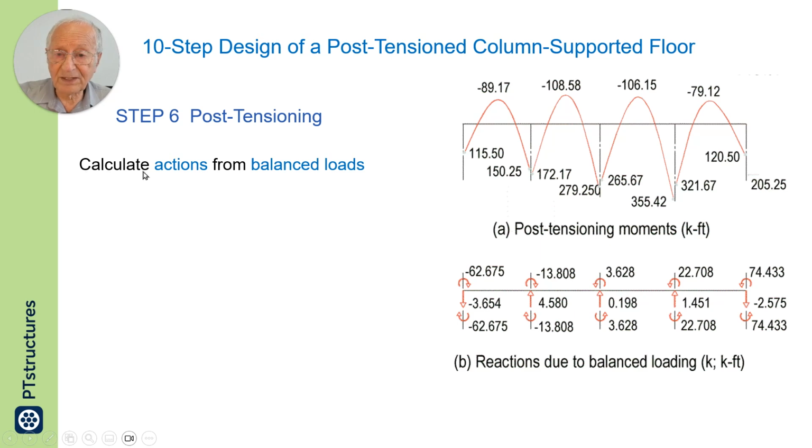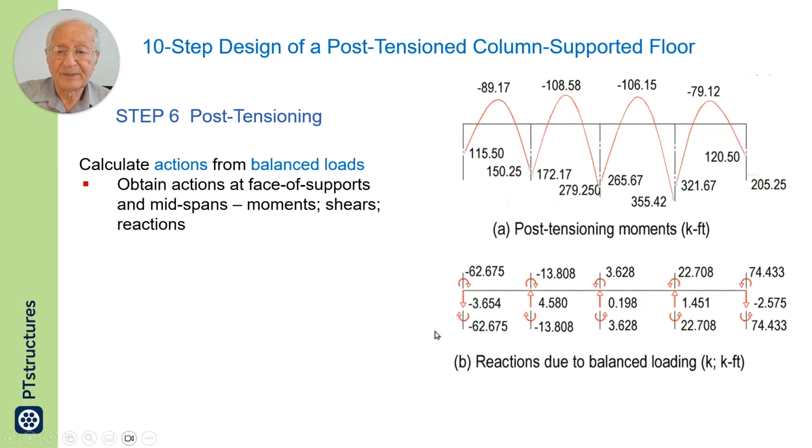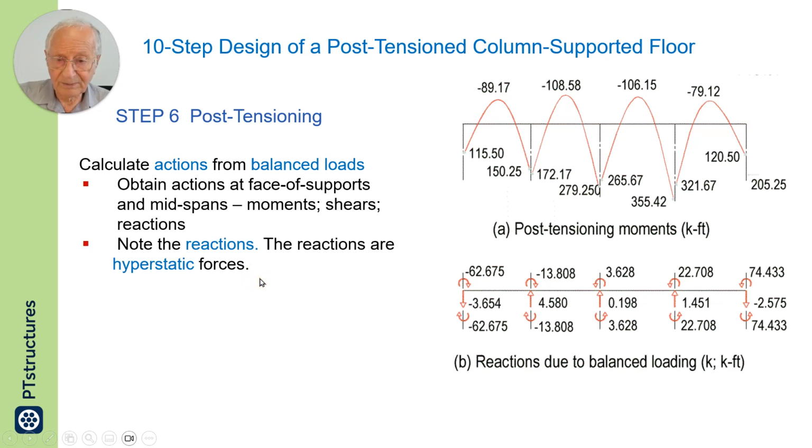The calculation is the result of us applying the balance loads of the previous screen to the frame of the structure. We obtain actions at the face of supports and at midspans for hand calculation. Face of support and midspan. If you have a computer program, it does it most probably at other points also.